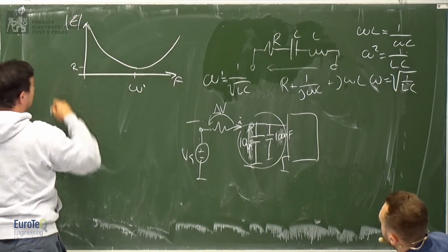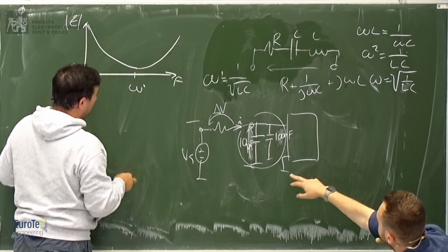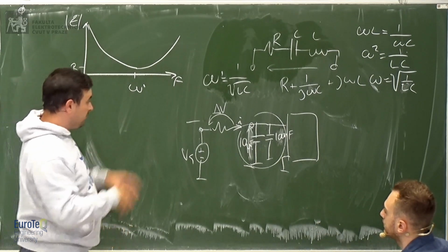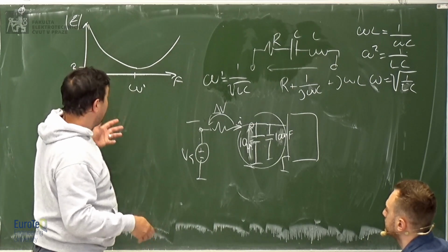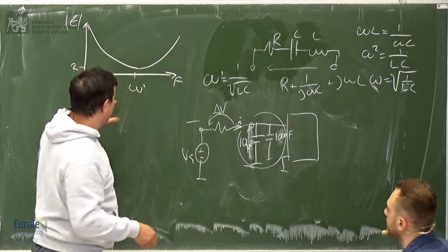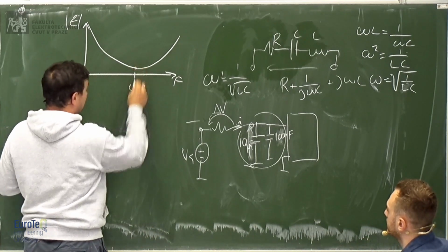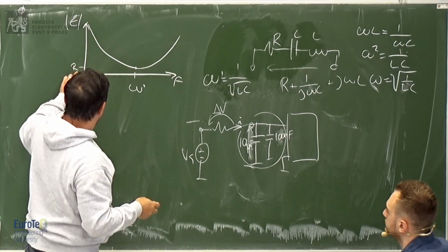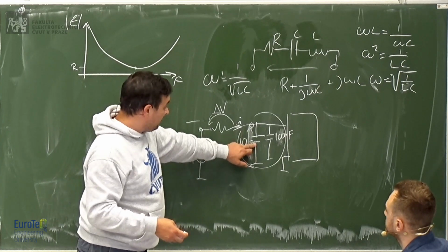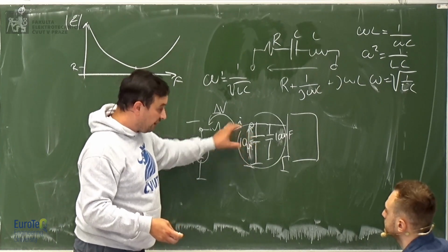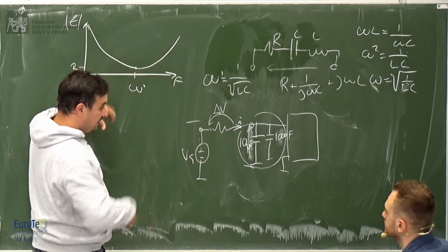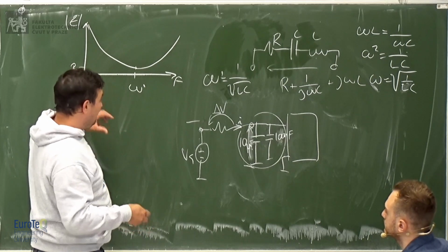And now these capacitors are going to have different L's, of course, because of the construction materials, the packaging, whatsoever. They will have different parameters, different omega 1. The purpose here is that we want this to be 0 at a specific frequency to remove that frequency. Ideally, let's say there is no resistance.